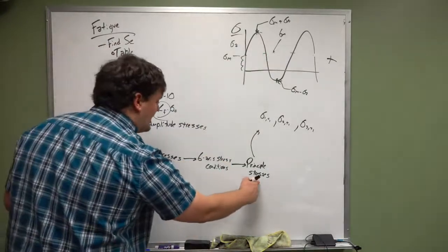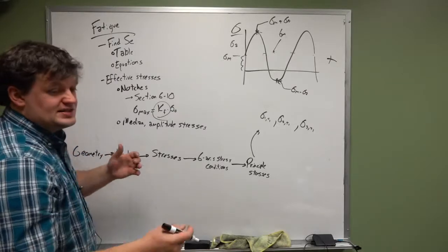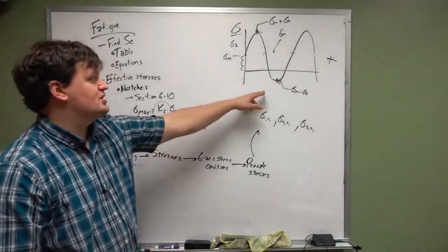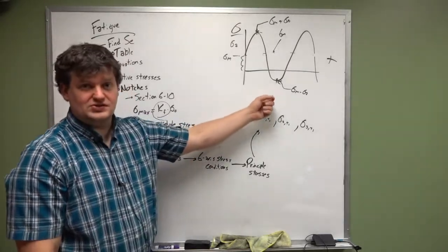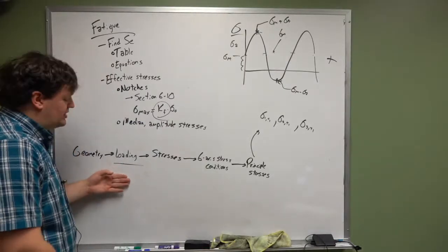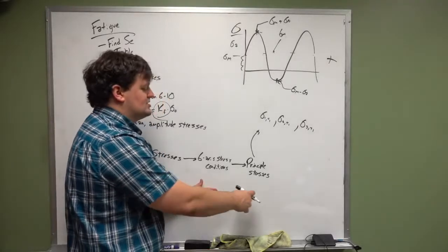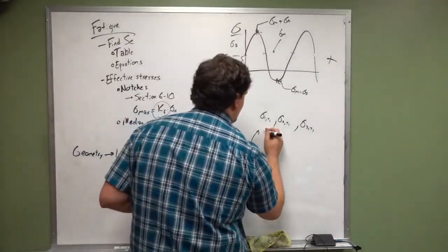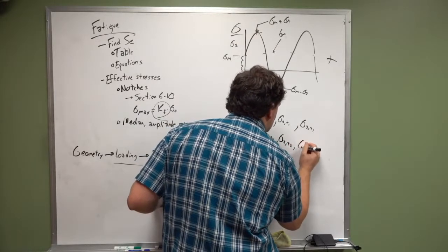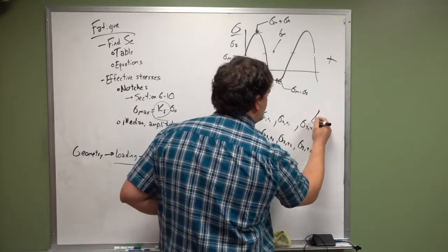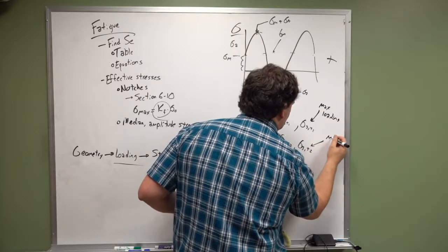Then you go back and do this again with loading in the reversed direction to find your minimum. Your minimum loading conditions are going to be your minimum stress conditions. So you go back to this point, look at the loading when it is a minimum, calculate the stresses, calculate the 6-axis stress conditions, and calculate the principal stresses from that. From that, now you have sigma 1 at t2, sigma 2 at t2, and sigma 3 at t2, where this is max loading and this is min loading.